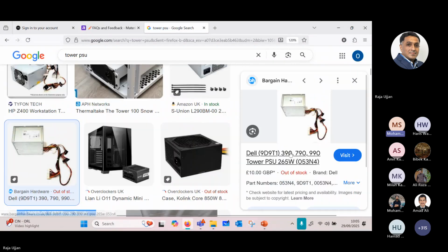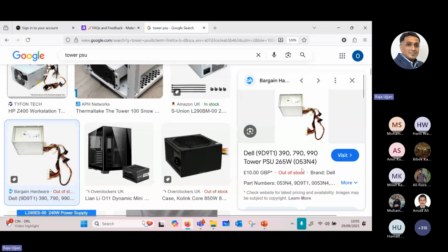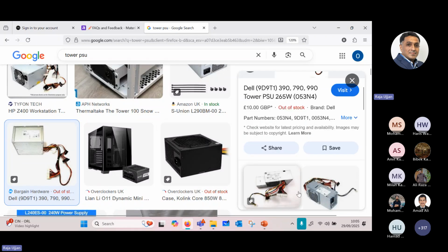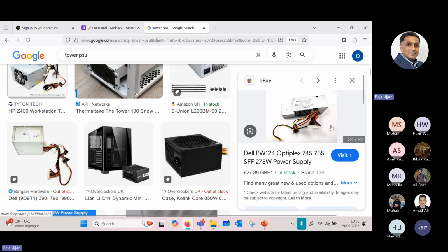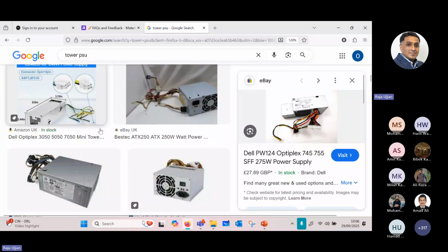Yes, sir. Okay, so you have used it. Any power supply, I'm not asking about Dell or HP, it's almost the same. There is no difference at all. This power supply has 18 connections, someone has 20, someone has 24 connections of physical connection. You connect it to the motherboard, your tower board. Have you checked this power supply before with the voltage? If you have checked, what was the voltage?